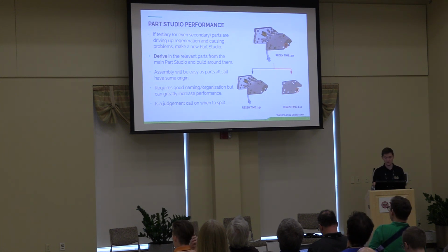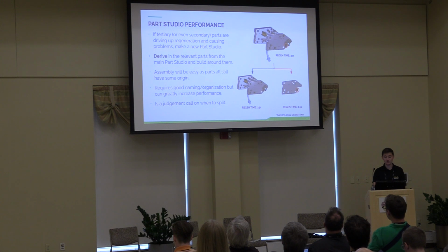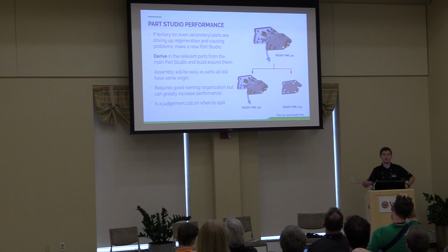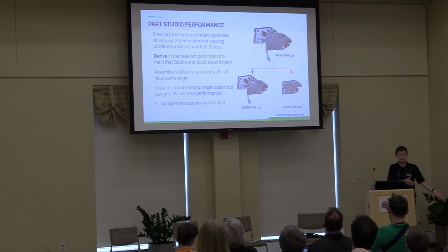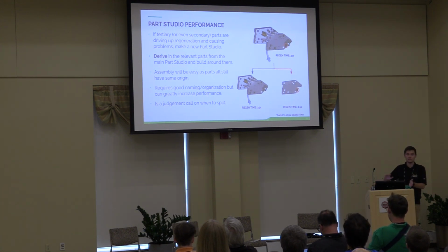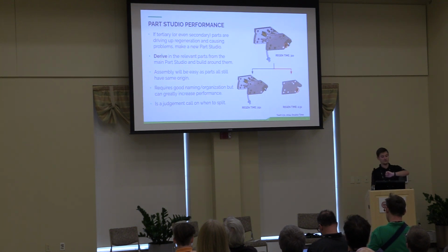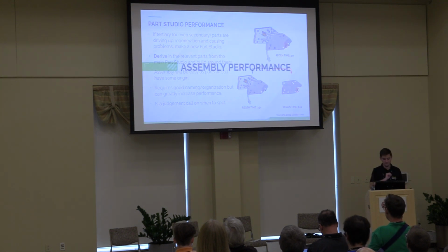As an example, this is their shooting system that was on the elevator of their 2024 robot. I took a look at the loading time, and this bevel gear was actually taking like 4 seconds. And yet it is such a small component of all of this. When you break it out, the regeneration time goes way down by just moving the bevel gear into its own location. So again, it'd be nice if it was all there, but if you're running into regen times and things are slowing down, you can just move it out, derive the references you need, and leave it in a separate part studio.